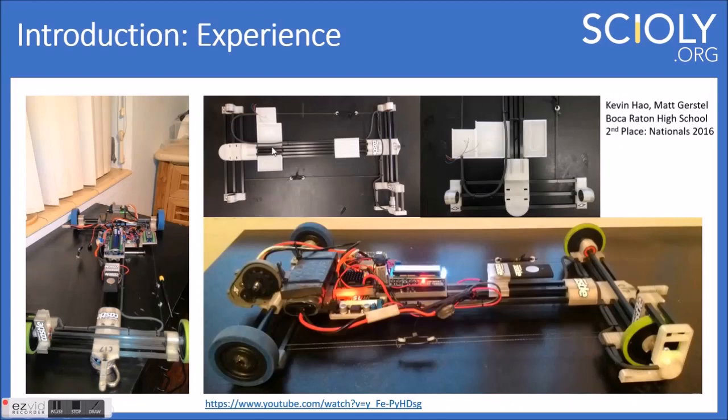You can also see the wheelbase, which is the distance between the front and rear axle, and that's connected by these 5 carbon rods here. It's a little bit hard to see in this top photo, but if you look down over here, you can see how it's almost like a pyramid shape, just missing the top rod. The reason we went with this kind of weird design for the chassis was we wanted some flexibility in the frame to compensate for any imperfections in the track. It worked out really nicely, and it was quite light, very strong, very flexible.